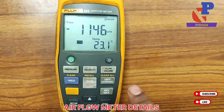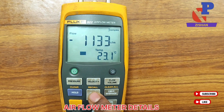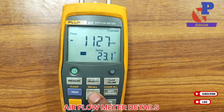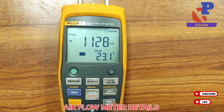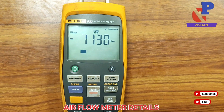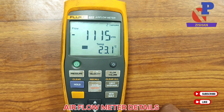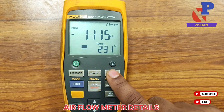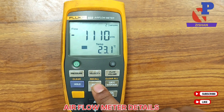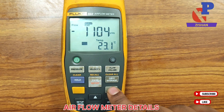To clear all, we have to press the yellow button, and after that the samples are cleared. For different flow samples we can just press the save button so that our data is saved. After that we make it average so that we can take the average CFM inside the duct. We can also clear all the data.